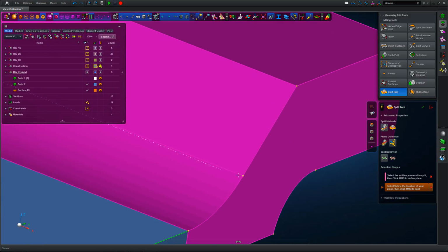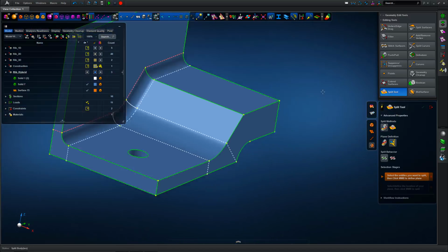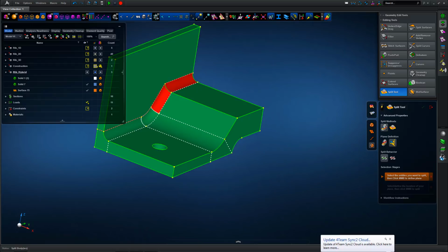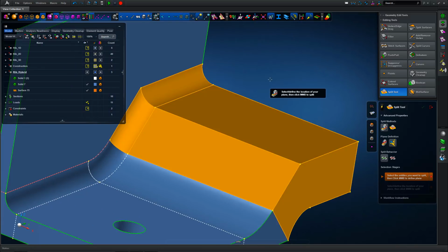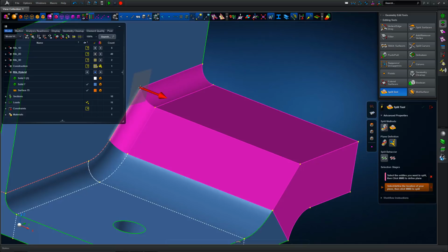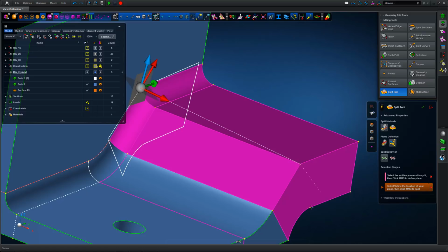So this is just a simple technique of breaking up the solid to give us the hex mesh that we require. Just a different approach to the tet mesh algorithm that we looked at in the last example, but a useful technique if you are maybe looking at models with trying to optimize the number of nodes.